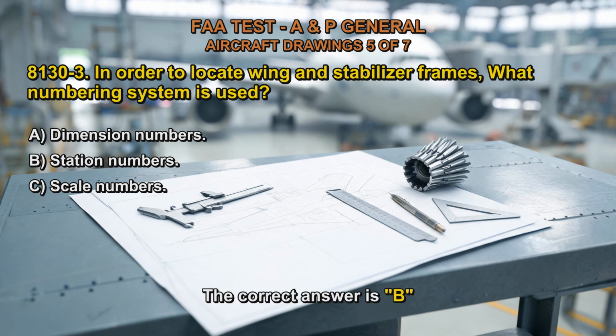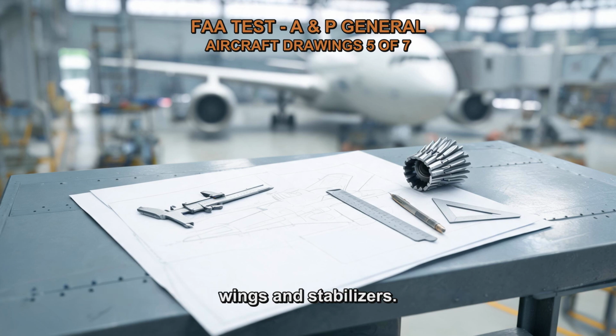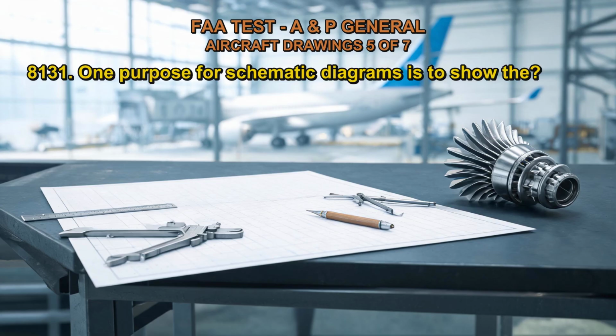The correct answer is B. Station numbers are used to identify specific locations along the aircraft's longitudinal axis, which includes the wings and stabilizers. Dimension numbers are used to indicate specific measurements, while scale numbers are used to indicate the ratio of a model or drawing compared to the actual size of the aircraft.